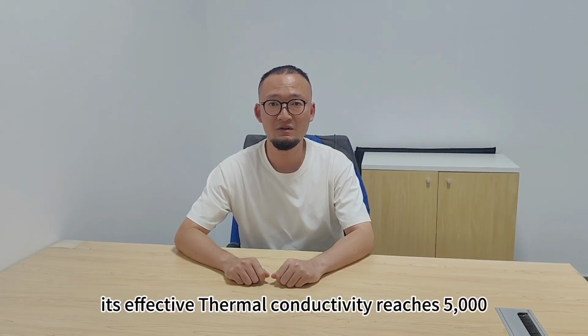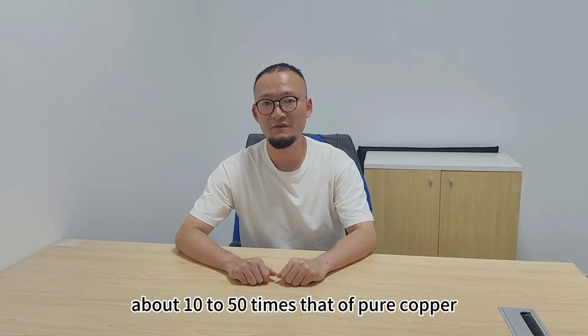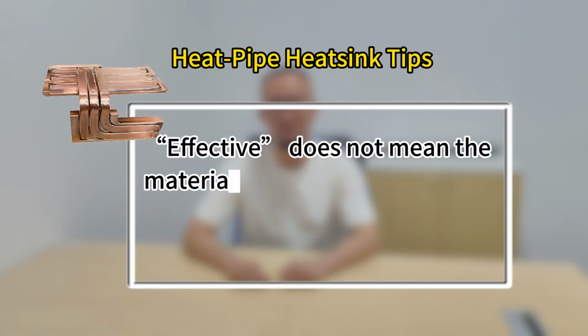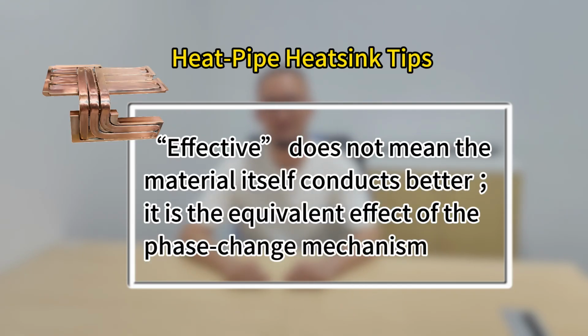Its effective thermal conductivity reaches 5,000 to 10,000 watts per meter Kelvin or more, about 10 to 50 times that of pure copper. Note that effective doesn't mean the material itself conducts better. It is the equivalent effect of the phase change mechanism.